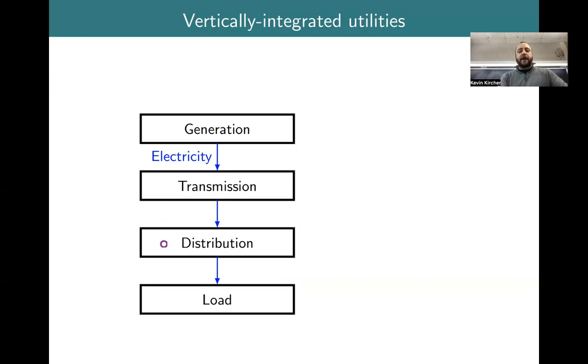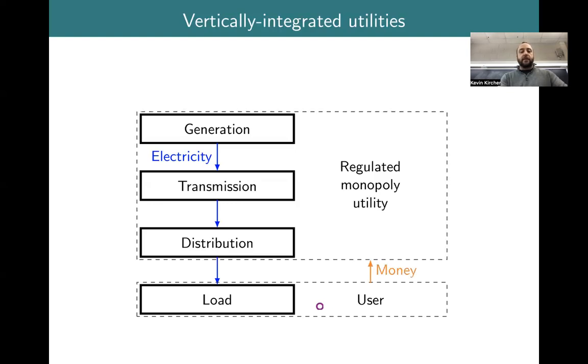The transmission system feeds power into the distribution system, which is typically at a medium voltage. So this is on the order of 100 kilovolts. Distribution will typically be on the order of 10 kilovolts. And then that will go to loads. These are buildings, factories, and so forth. And typically they operate at low voltage, so on the order of 100 volts. So in this model, basically users, people who pay for electricity and the services that we get from it, usually are in buildings, but again, manufacturing facilities and things like that. And we are responsible basically for the loads.